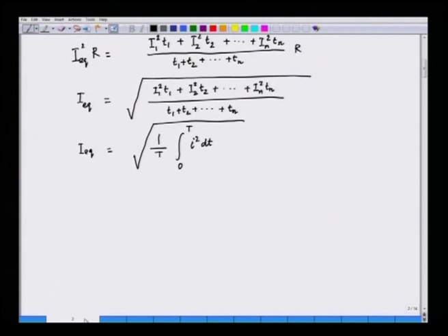Now that we have found out the equivalent current, we do not have any more the discrete nature. The current is although varying, we have been able to find out an equivalent current. So, the next step would be to find out the rating of the motor. Now, the motors are not the same. DC motor is different from induction motor is different from synchronous motor. So, definitely we would like to choose the next higher current rating or the next higher torque rating.